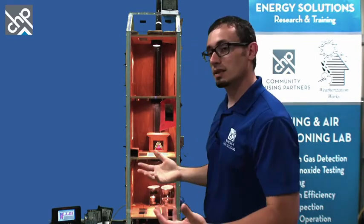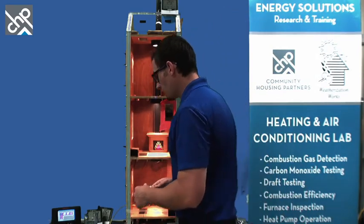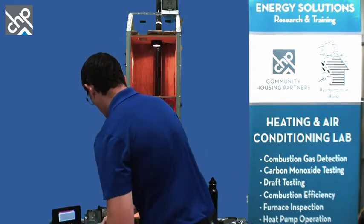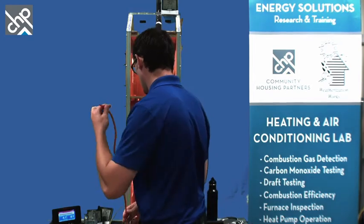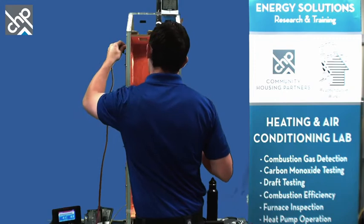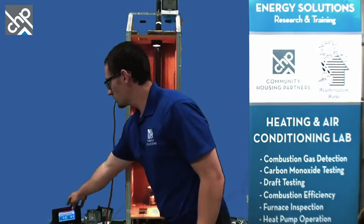But what good is indoor air quality if I backdraft my furnace, right? Backdraft my water heater, cause these issues. So let's take a look here. Look up my pressure gauge throughout the building. We'll do a pressure gauge top and bottom. How about that? Pressure gauge.